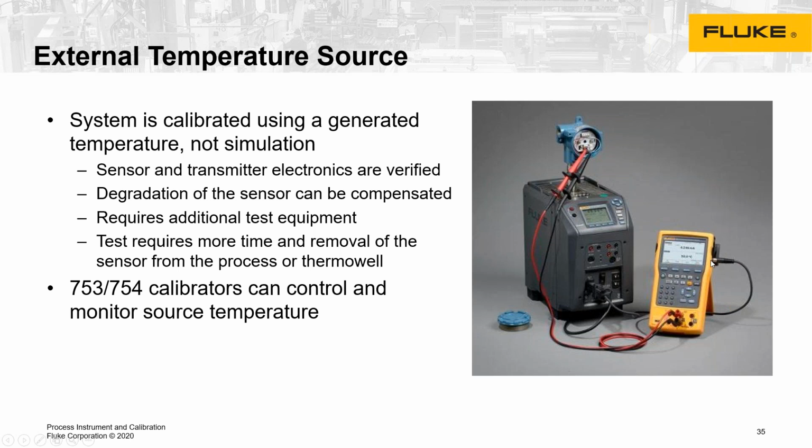The 754 and 753 in a temperature scenario are actually capable of connecting to Hart Scientific or Fluke Calibration dry wells and micro baths. With this added serial cable, we can plug into the side, and that would allow us to drop an actual sensor into the device and heat it up to a certain temperature. The 754 will control the temperature output of the dry block or the micro bath, as well as measuring the electrical feedback.